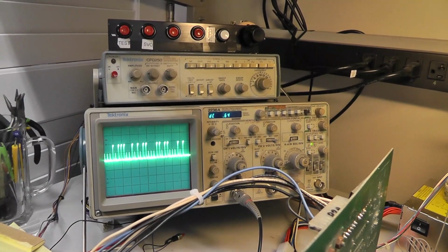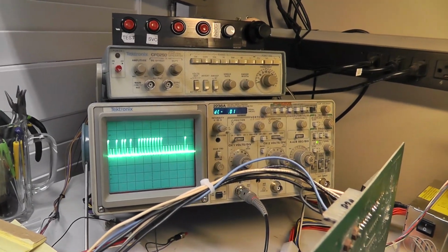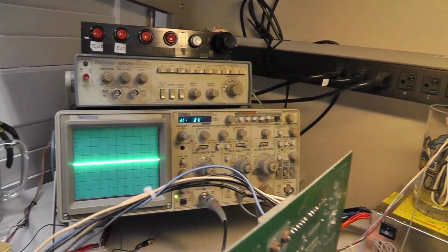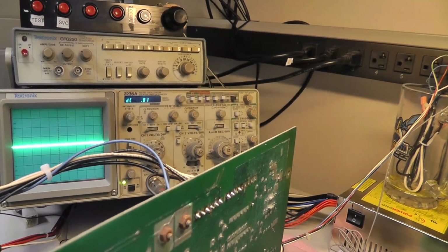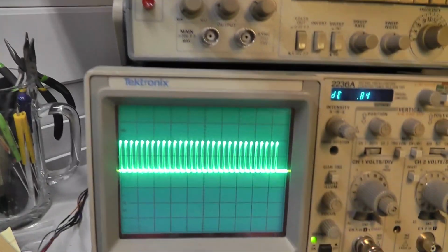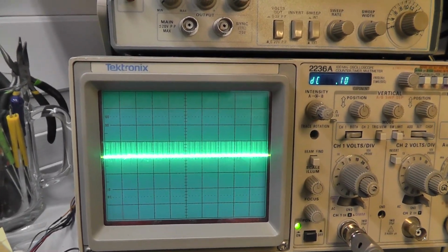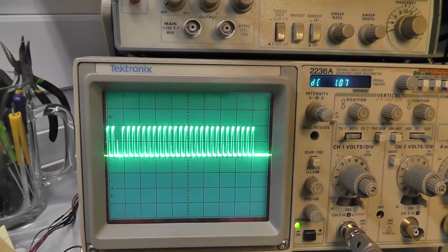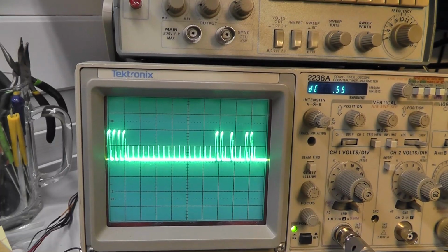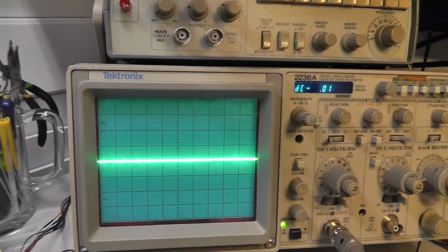Then there's data line 1, data line 2, data line 3. Pin 9 is high, which is VRA, and I'm not sure what that is yet. Pin 1 is grounded. Pin 2 is data line 7, which obviously looks ideal to me. Now that's data line 6, which looks kind of odd to me. That's data line 5. That one's kind of weird. That's data line 4. I don't know what pins 6, 7, and 8 are.